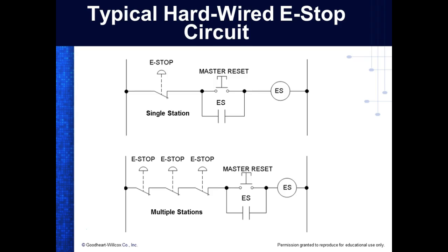So it uses a double pole contact in there. One of them powers the light and one of them breaks the circuit. So when it's out, it's actually lit, right? You understand? But now the e-stop button, the actual button itself, has to be red, and it's got to be against a yellow background. So that's the rules now. Of course, in the older buttons like this, you won't see the yellow background. All your new ones, you'll see the yellow background, usually just a little ring or something. Might have arrows on it that tell you which way you need to turn it to unlock it.